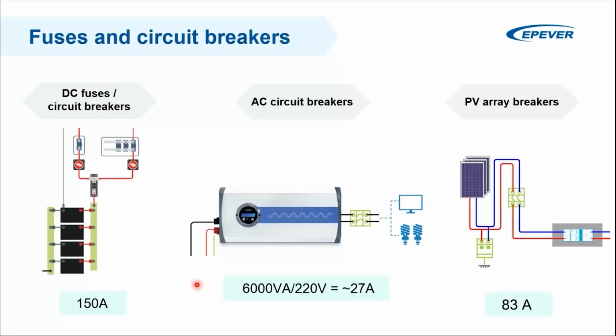So a DC circuit normally contains a main battery fuse, which is here, after which it branches to the individual users. So here I've applied, just for example, a fuse for the inverter itself and a fuse for the charger itself. What is the advantage of this? Well, if there is a fault in the inverter, for example, this will be blown first, and this fuse will survive.